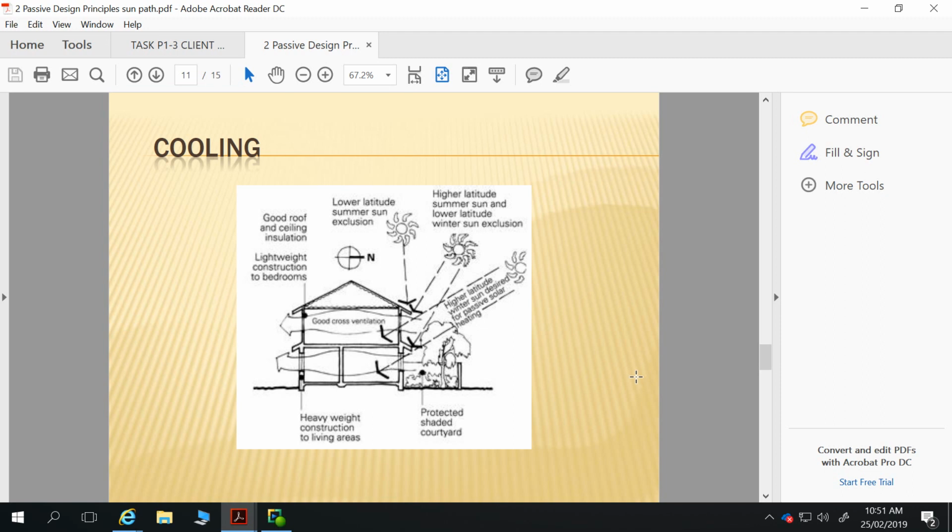For a tiled roof, you've got to have sarking underneath that tiled roof anyhow, because tiles are notorious for letting drips of water come through. We don't want any of those drips of water coming into our insulation on the ceiling, or even worse, on the plasterboard ceiling. But it's just a really good idea for a sheet roof anyhow, to have that sarking underneath, and a reflective foil sarking.